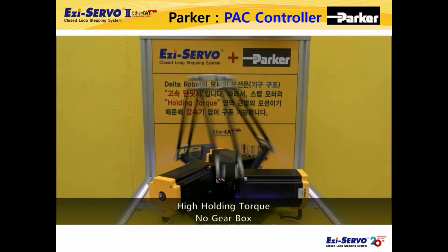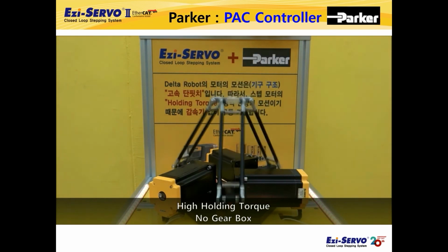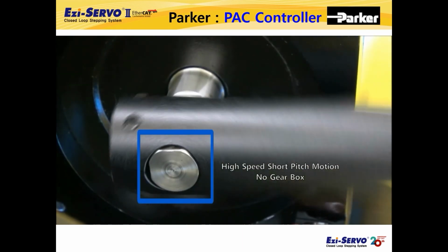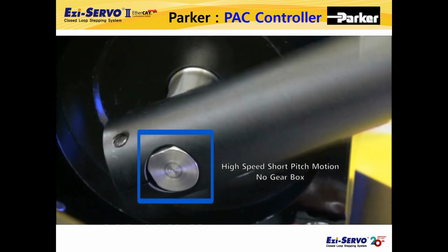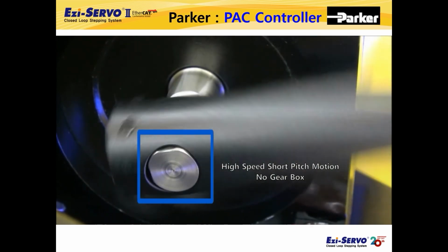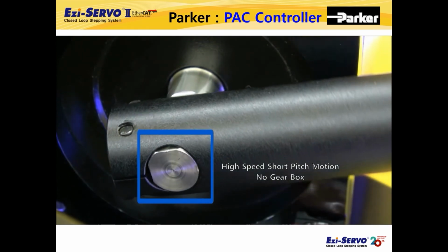On the other hand, stepping motors have a holding torque that generates the maximum force when stopped, so stepping motors can stop without hunting even without a gearbox. Thus, the robot can be directly connected to the motor shaft without a gearbox. If you look at the actual motor movement, it is a short pitch motion. Stepping motors are optimal for short pitch motions like this.